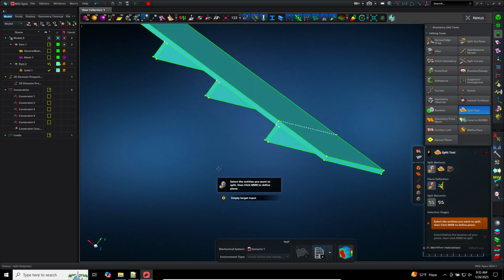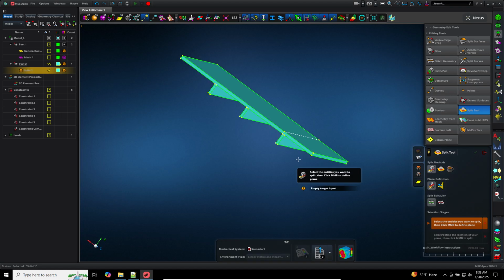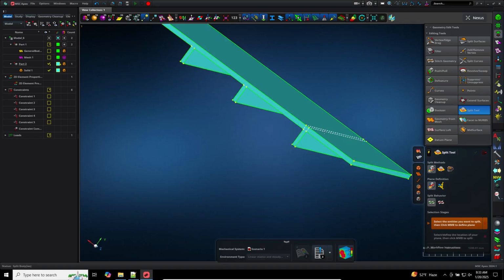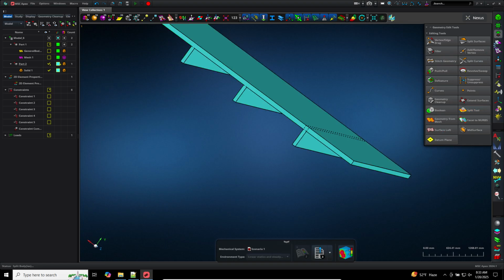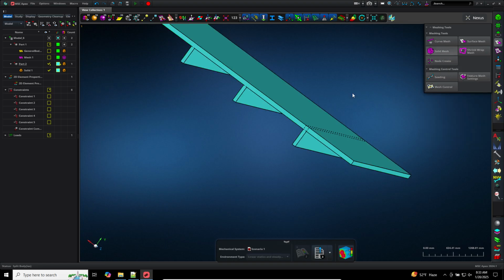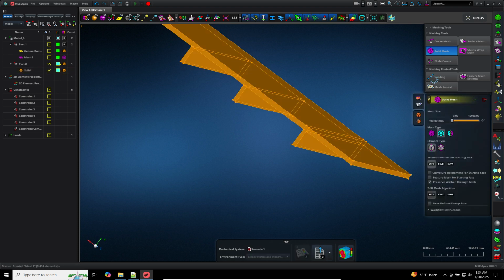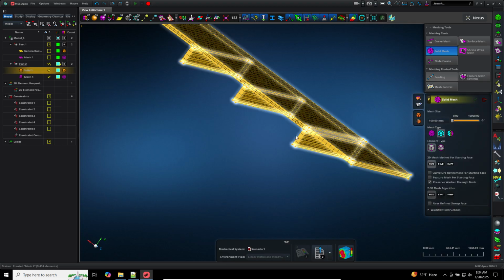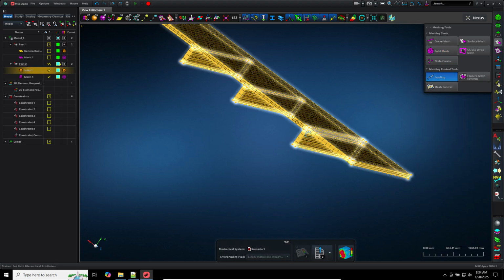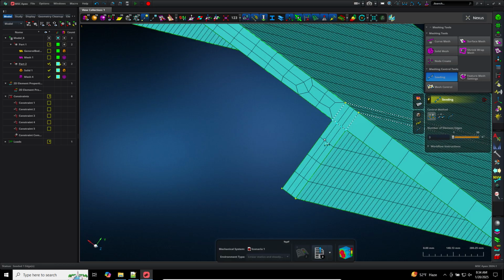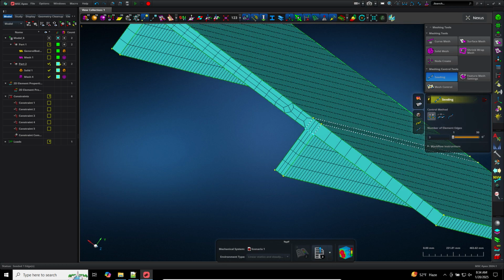And let's look at this. Okay, that looks a little better. Let's click this. And here, let me show you what the outcome of this action is. So if I go back to the mesher, let's go ahead and use 3 elements through the thickness here. Let's click this edge. And now I get 3 elements through the thickness for this one stiffener. So that's what I want.